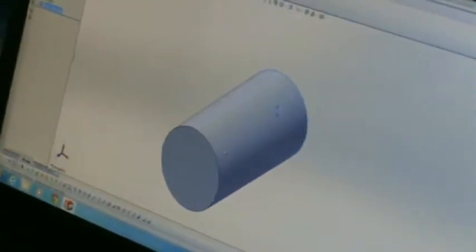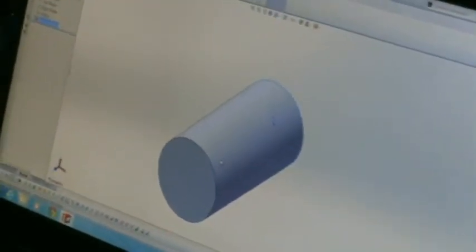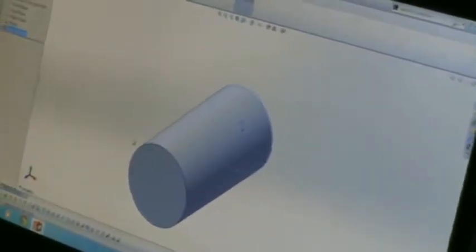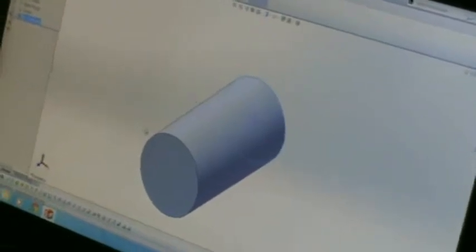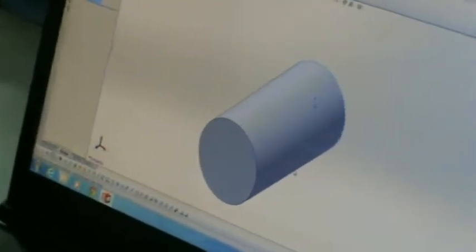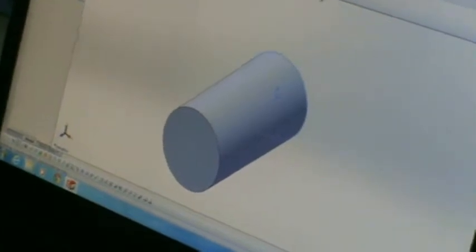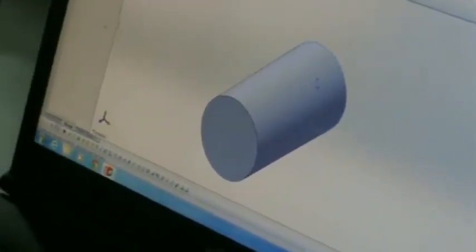Okay. This is one easy way to make a cylinder, but not my favorite one, because mostly we have a cylinder with a hole in it, with some lines, different diameters on it. So we can put it on immediately in the sketch. Because afterwards we have to open one sketch to change every diameter. Otherwise we have to search in the feature manager. This is the feature manager.